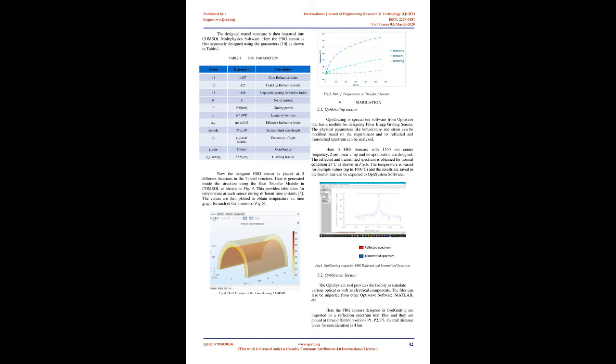They all are provided with the same center wavelength of 1550 nanometers. The input is provided to the 3 FBG sensors through 3 light sources simultaneously, and the reflected spectrums of the 3 sensors are individually monitored through 3 OSAs or a WDM sensor interrogator as illustrated in Fig.1. In practical conditions, instead of using 3 separate input sources, a single source can be used which can feed all the FBG sensors. Fig.1: block diagram, ideal condition.